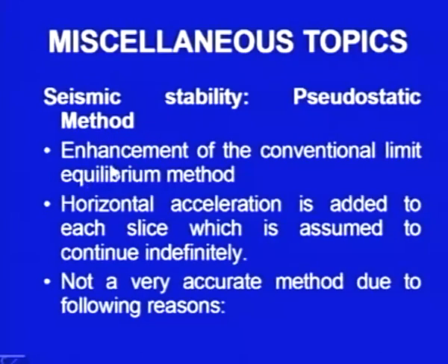It is an enhancement of the conventional limit equilibrium method, and as we did in that problem, horizontal acceleration is added to each slice. To each slice we add some component which is assumed to continue indefinitely.